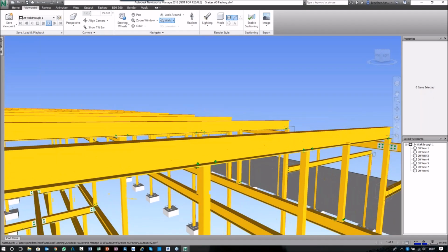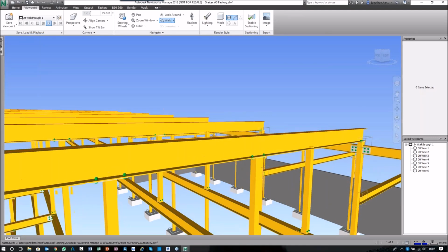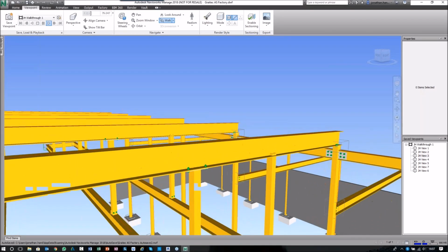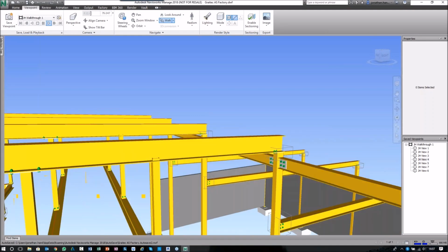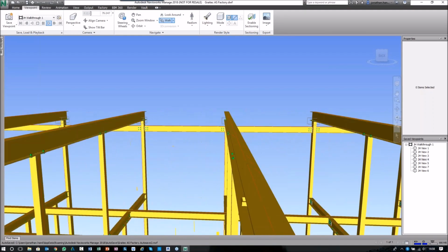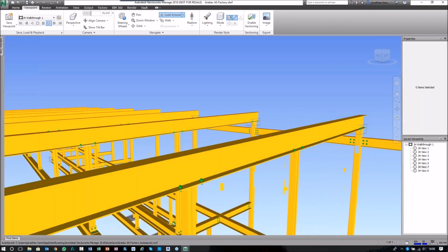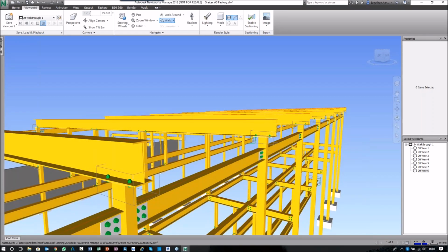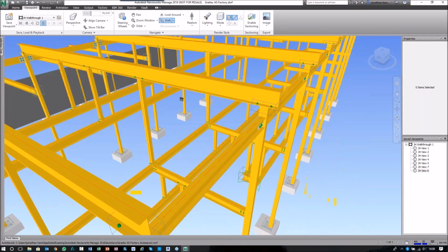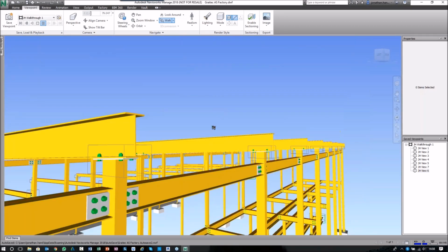Again, I've done this pretty quickly, but you can start to see that Navis can really quickly render this up. And it just spins around, it visits all the views that you want, so you can go up and down in the model, orbits about, but you really do get a full idea of the scale and size. That's another really cool, exciting feature that you can start to utilize. And you can see it's really quick. Just go in, save the viewports, and then orbit the model, and then create your little walkthrough.